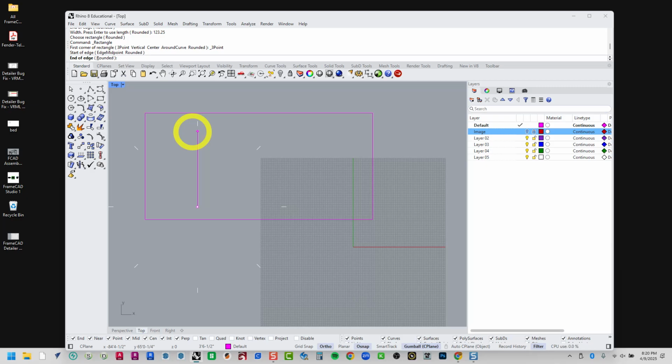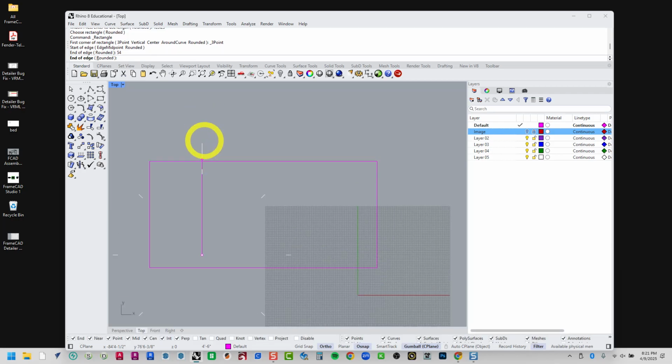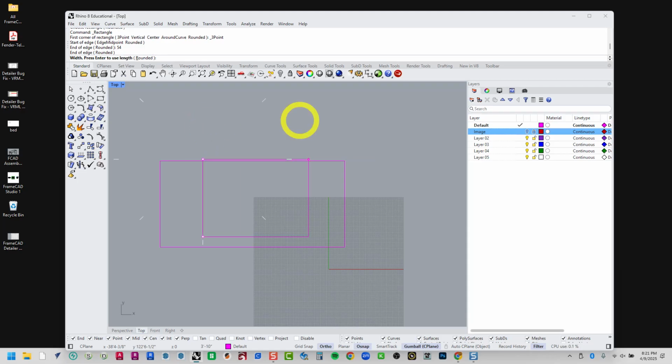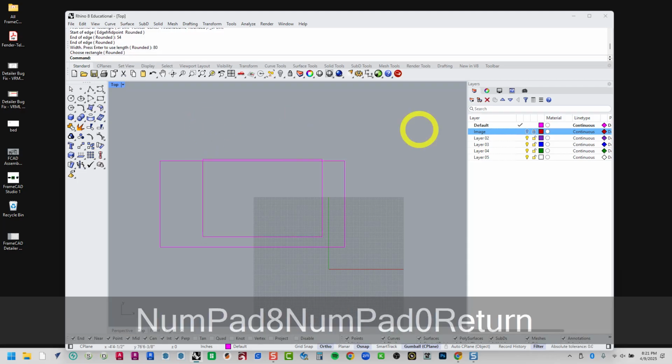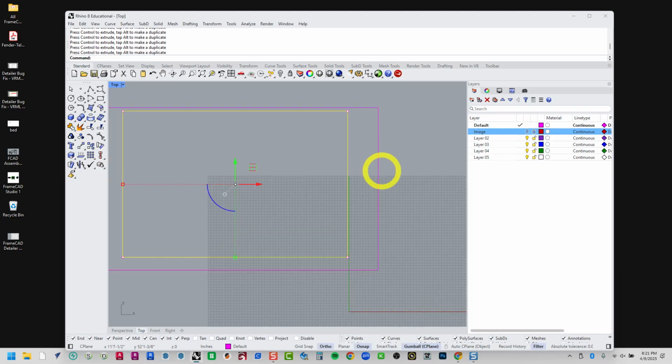Where do I want my bed? Somewhere in the middle, I guess. Towards the back, towards the front. All right. So this is 78, you said? Edwin? I mean width. This was a 48, 54. Okay, 54. So if I move this so it lines up with this edge, I can measure how much extra space I have now that I've put in this huge bed, right? I can type in D or just type in distance and you can start to measure things. I'm going to measure from this end point all the way to here, and that leaves me with 6 inches.